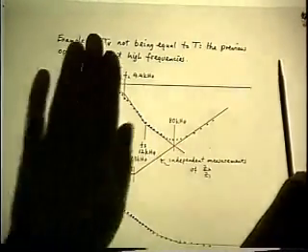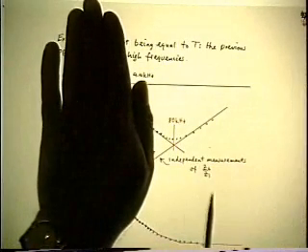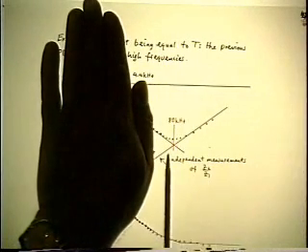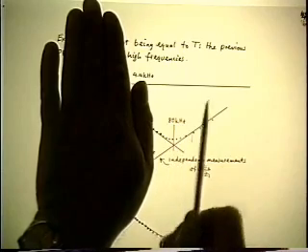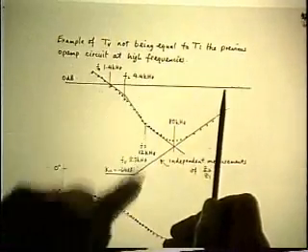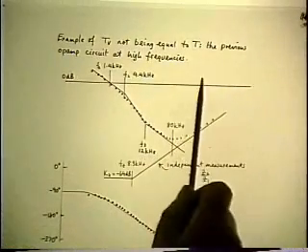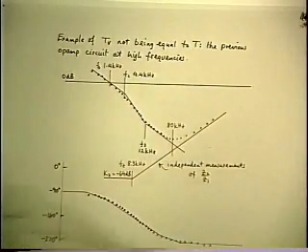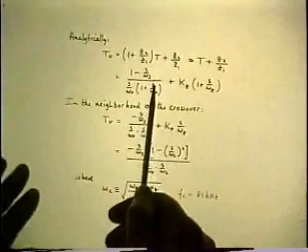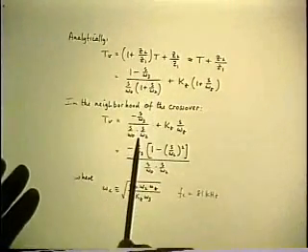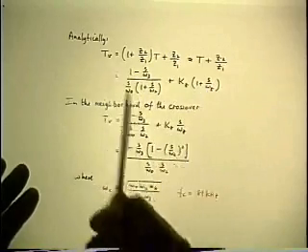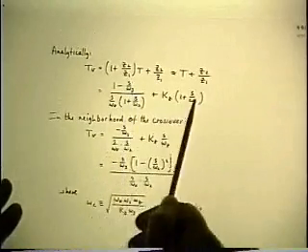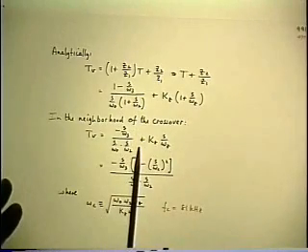So I don't care about what goes on down here. In other words, I can approximate the analytic expressions to be valid only for frequencies which are much higher than all three of those corners, which is what I've done right here. This is the same expression, except I've simply dropped the 3 ones, which is okay as long as S is much bigger than all 3 corner frequencies.